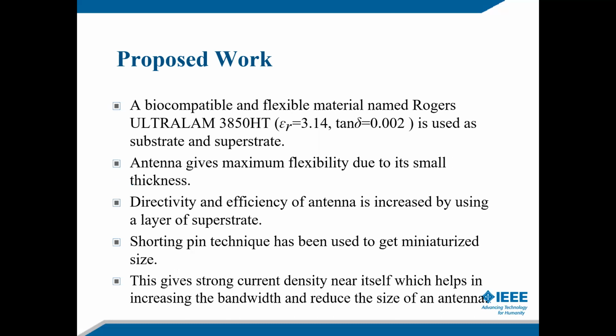We are using the dielectric material Rogers Ultralam 3850HT, which has a dielectric constant of 3.14. The same material is used for the substrate and superstrate. Why are we using this material? Because it is biocompatible and it is a flexible substrate recommended by the manufacturer, Rogers Corporation. It gives flexibility due to its thickness. The thickness of this substrate is 0.1 millimeter.